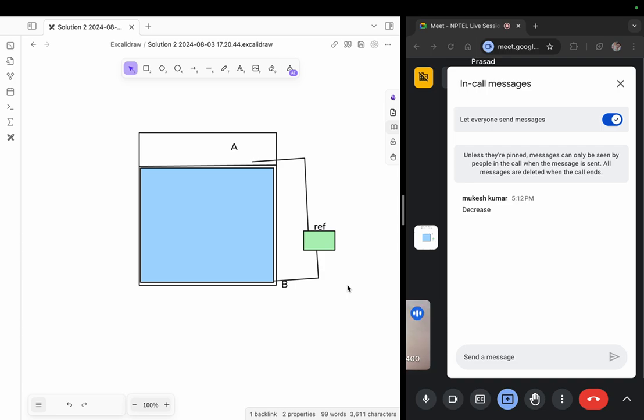Now I will take the same pressure gauge and compare it with a known pressure value, so from there I will assess what the reference value is. Let's say the gauge is already compared with the known atmospheric pressure. So what I will do is leave the other end open to atmosphere always, so that I can calculate the absolute pressure directly.